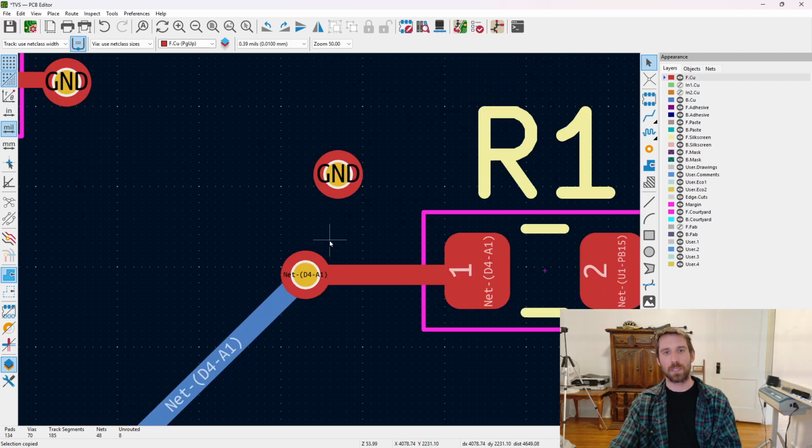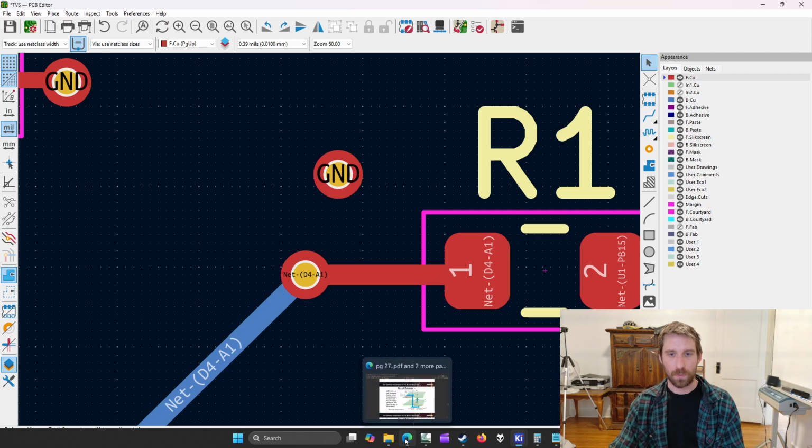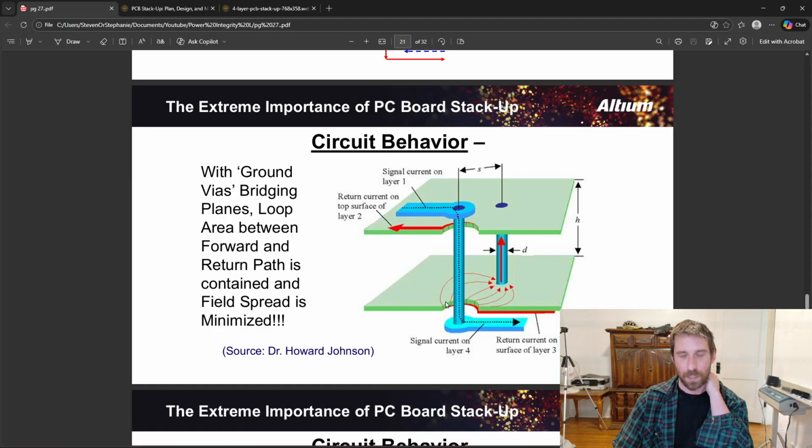So in this line of work, for something like this, just doing this at all will annihilate most beginner and intermediate engineers. So there's that. Another advantage of having two ground layers is that if you want to convert a 2-layer board to a 4-layer board, the easiest way is just two ground planes. If I have a power plane, now I got to connect to it and worry about that. But if I have two ground planes, well, you're already going to have vias and stuff like that. So you can just pretty much add it, and then you're done.